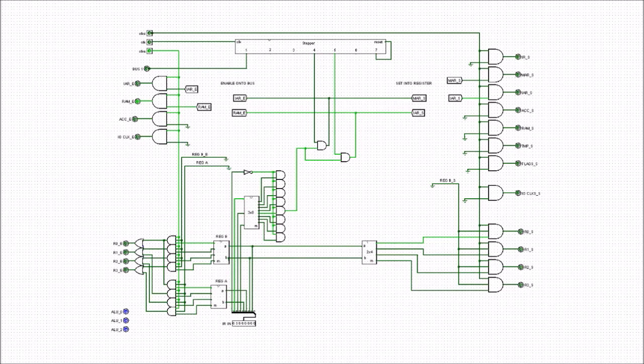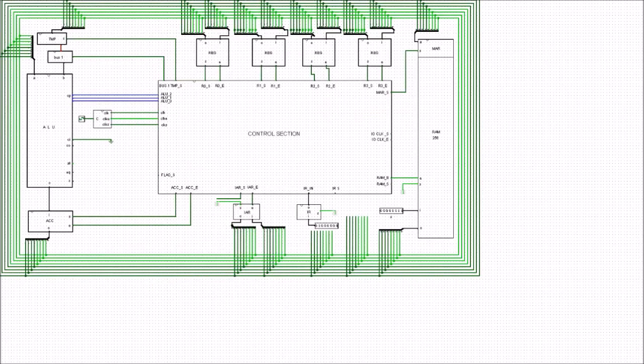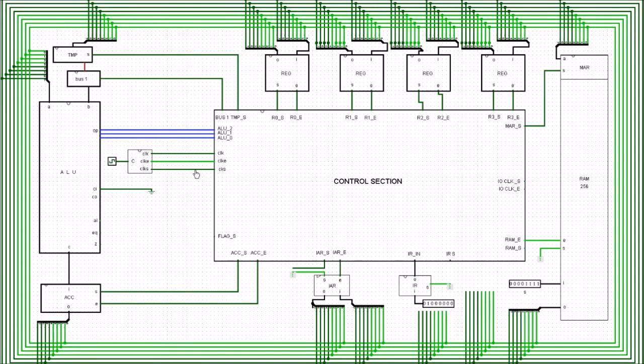So we're going to the top level again, and finally when the clock goes to set, then that value has been set there, and the value 15 now goes into the instruction address register. So it means that the next instruction that you're going to execute in the control section doesn't come from memory location 2, it comes from memory location 15.